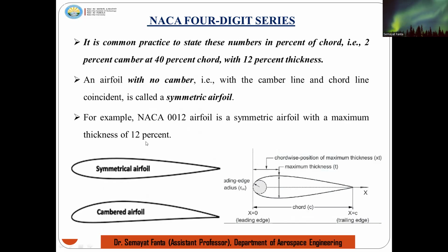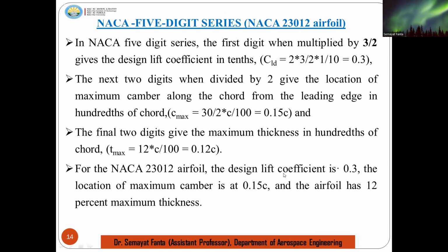We have only a thickness of 12% of the chord. Okay, maximum thickness is located somewhere, which is represented with chord. The next is the 5-digit series, NACA 5-digit, 23012 aerofoil.